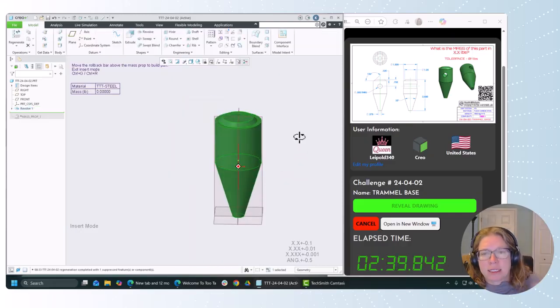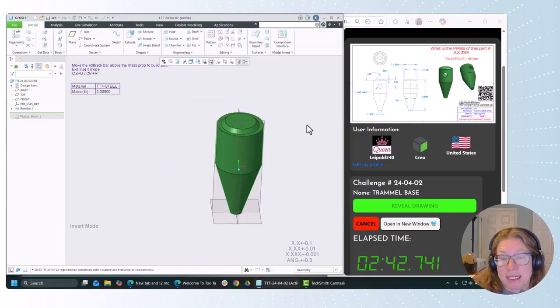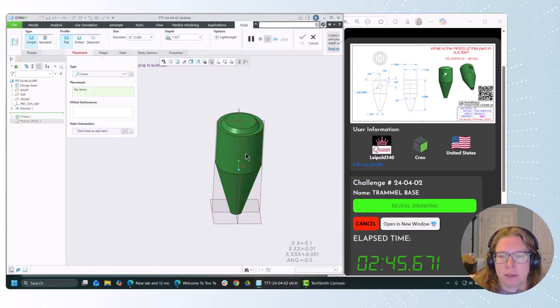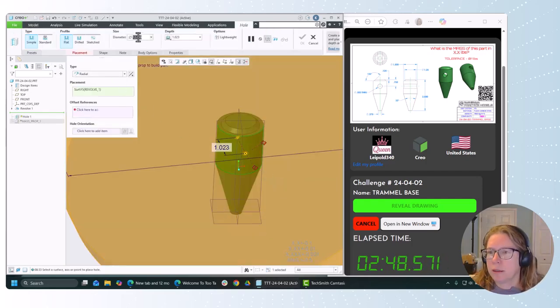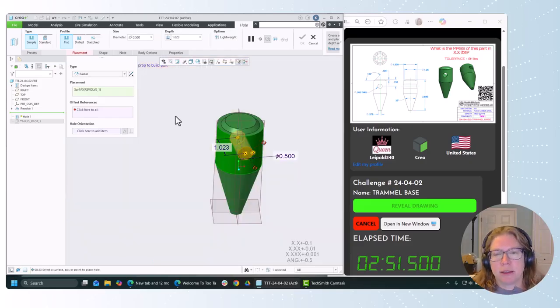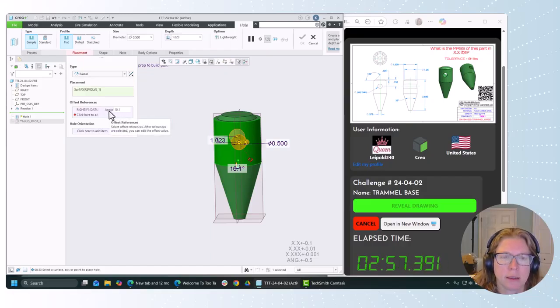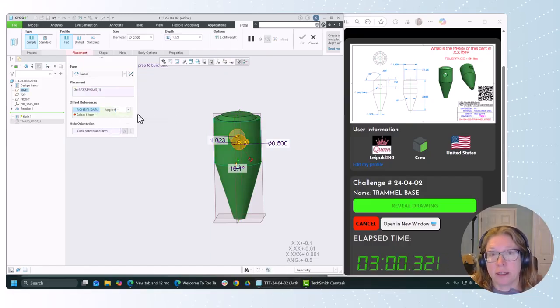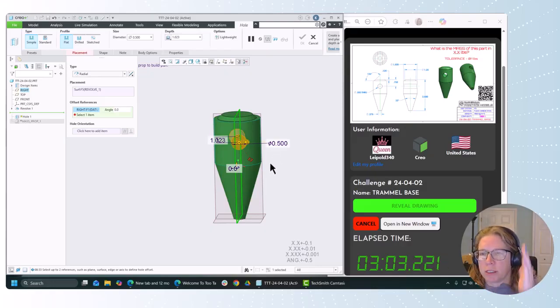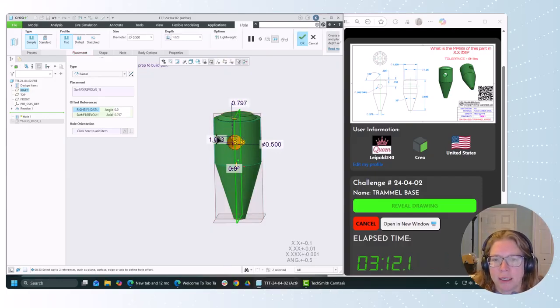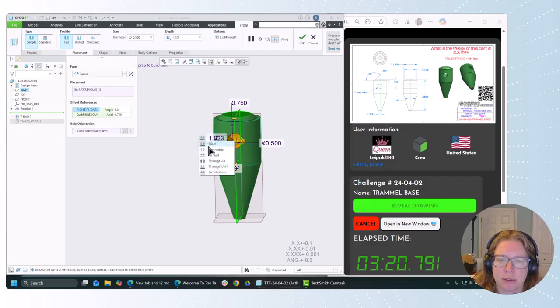So always need an axis of revolution when you're doing a revolve, and if you make the sketch inside the revolve, then it will automatically give you those diameter values. The diameter here is 0.5. Okay, so we're on a plane, so I'm referencing this off of the right plane, and we're going to be 0.75 down from the top. So we'll drag our selection drag handles, make this 0.75, diameter is 0.5, and let's set the depth to through all.